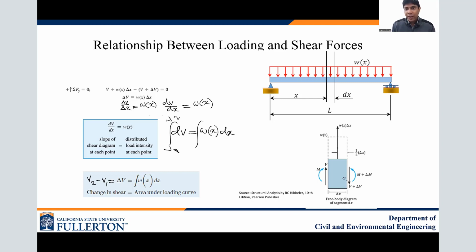So that is another way we can express our relationship between loading and shear forces. The change in shear between the points is equal to the area under the loading curve, and the loading curve is due to the distributed loading. Now our aim for the next part is to establish the relationship between shear force and bending moment.